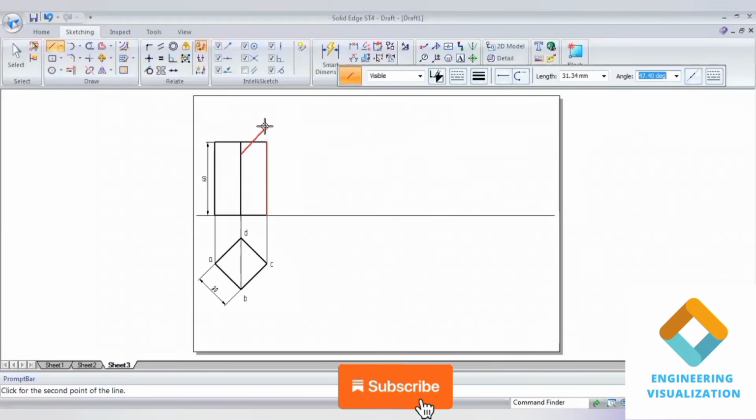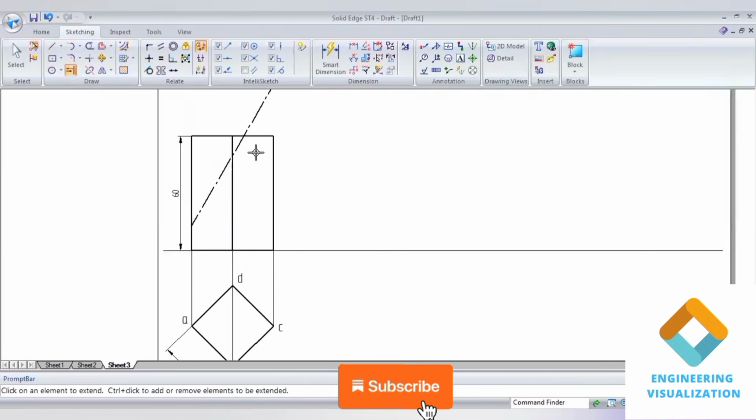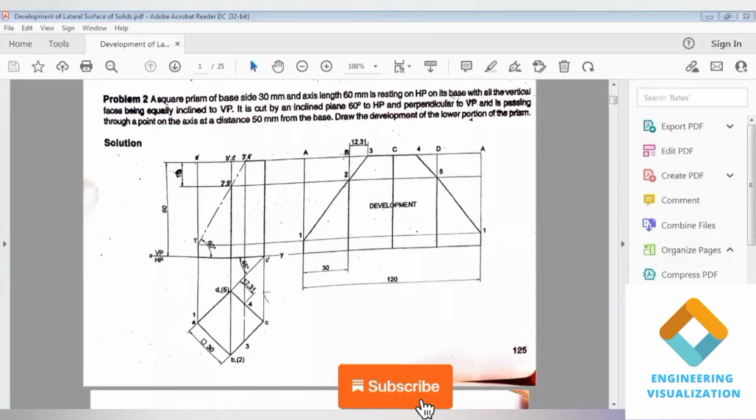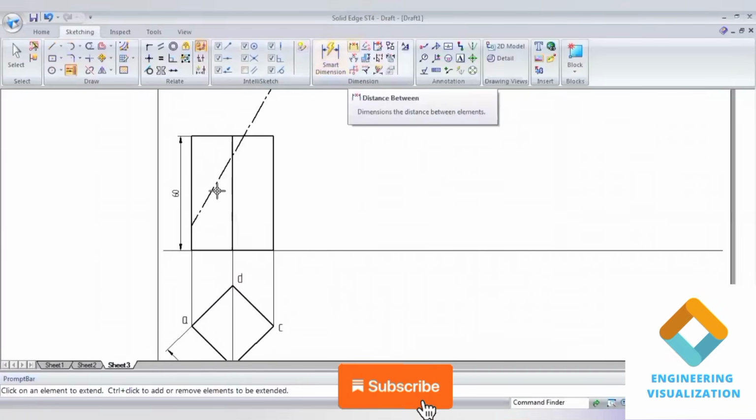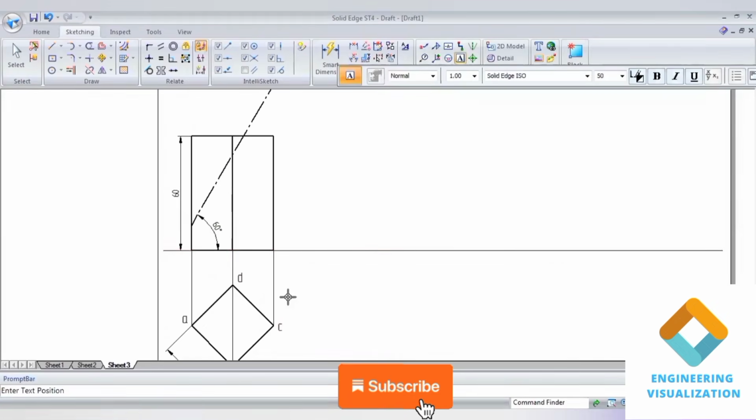Then I am drawing a section plane, taking this as the axis plane, now giving the angle 60 degrees. That's what I can see, the angle of inclination will be 60 degrees here. So type 60 and enter. After this go to next and extend this line. This is where it is cut. Now we can show the angle for this section plane. The angle of inclination is 60 degrees.